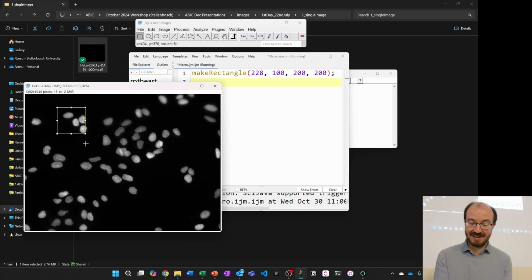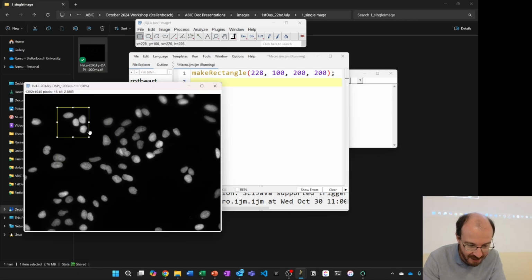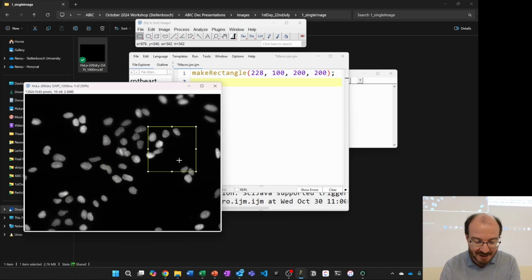So that's generally how I would do it. There might be a way to do it graphically speaking. For example, I think if you hold shift while you're dragging it, then it retains the aspect ratio. But I don't know how you start. I don't know, if you hold control, it does this. Oh, okay. If you hold shift, then it keeps it square. So it doesn't matter how you draw it. If you hold shift, it keeps it square. If you hold control, it enlarges it around the current position. Alt doesn't do anything. So yeah, that's keyboard shortcuts. They're helpful.